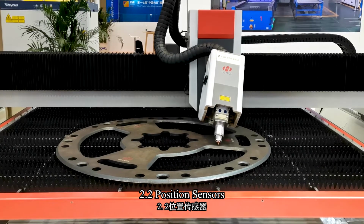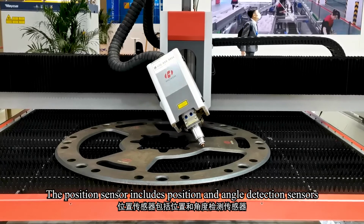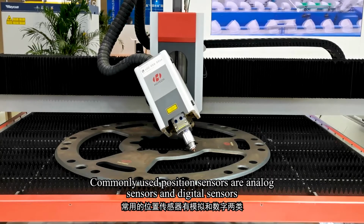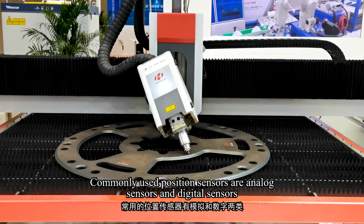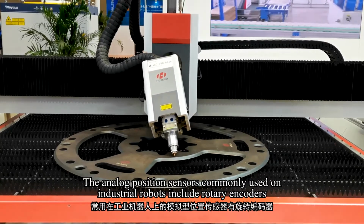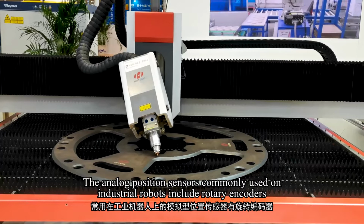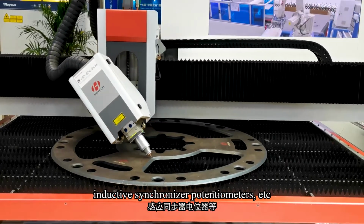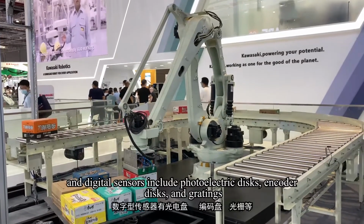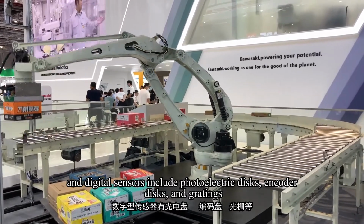2. Position sensors. The position sensors include position and angle detection sensors. Commonly used position sensors are analog sensors and digital sensors. The analog position sensors commonly used on industrial robots are rotary encoders, inductive synchronizers, and potentiometers, and digital sensors include photoelectric discs, encoder discs, and gratings.